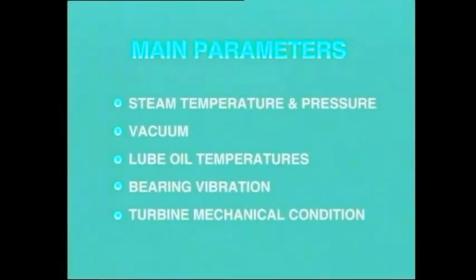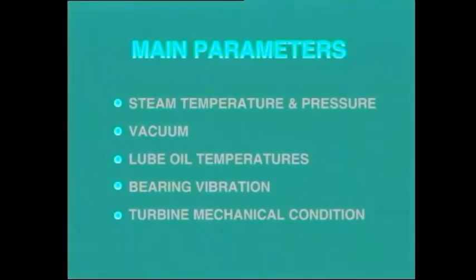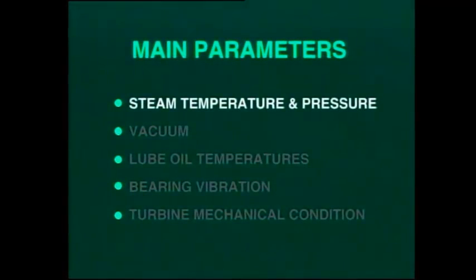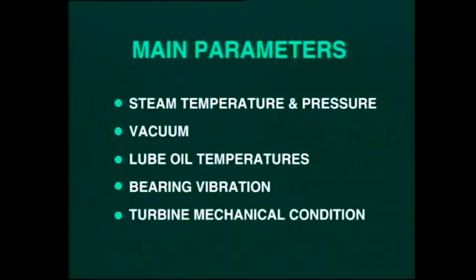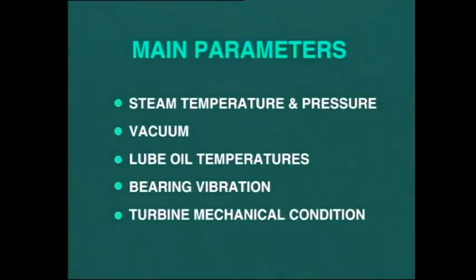Referring to turbine operation, the indications we are most interested in are steam conditions, that is, pressure and temperature, vacuum, usually dependent upon certain water conditions, lube oil temperatures, bearing vibration, and mechanical condition of the turbine as indicated by the supervisory instruments.